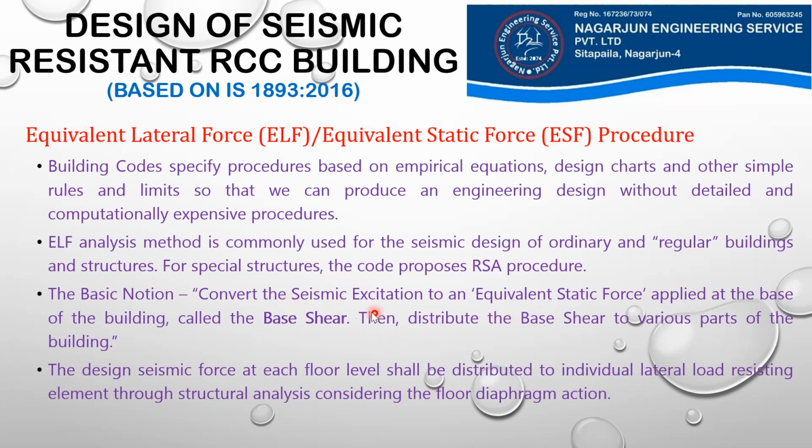First, the force is applied at the base of the structure, base shear, then that is distributed to different parts or different floor levels of the building, and from each floor level that force is distributed to individual lateral load resisting elements in that particular floor level, and that is done through analysis. That analysis is performed by the software itself, and after that force is distributed to individual elements, based on that force we will perform the design of the building. So this is the general methodology or general principle of the equivalent static force procedure or the linear static procedure.